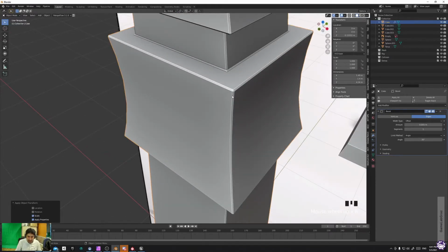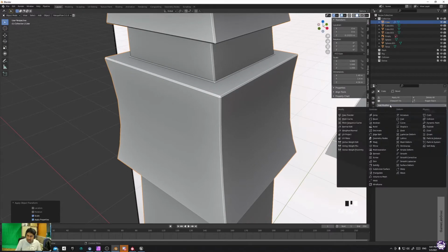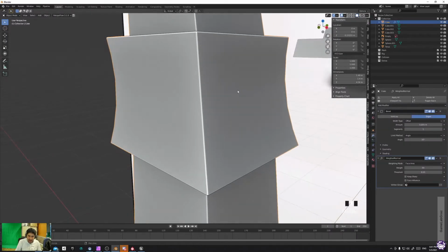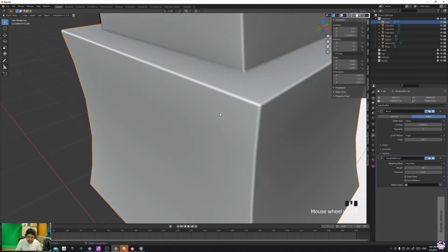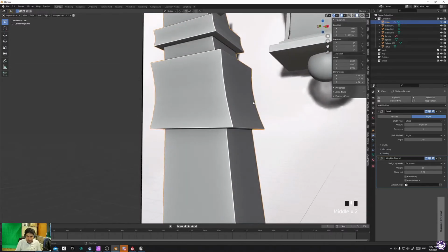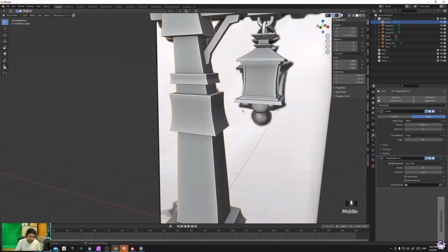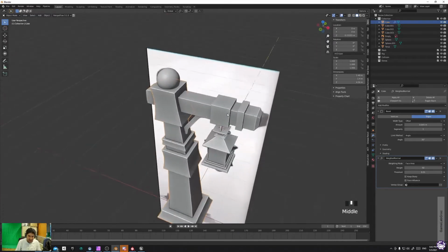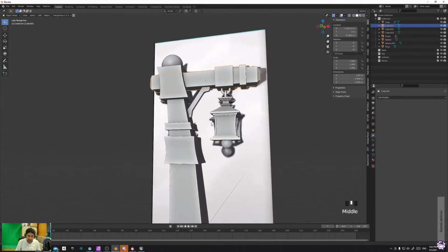After you apply the bevel, there is one modifier called weighted normals. It will smooth the edges, it will somehow interpolate between the values of normals again, but keep the rest of the shape smooth and sharp. It's very good for the metal material, but also in our stylized shape, I think it will work.